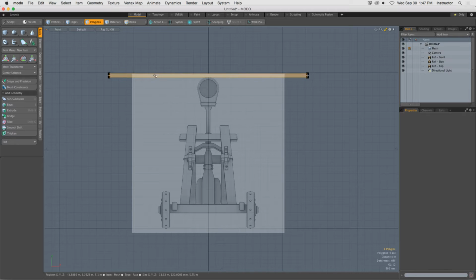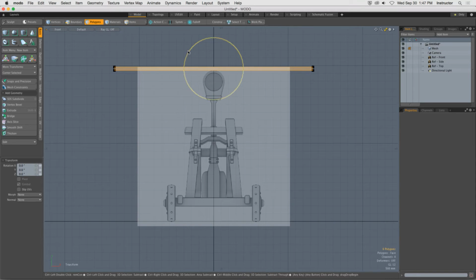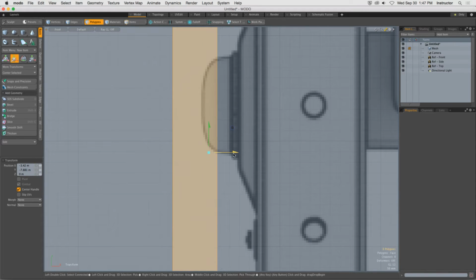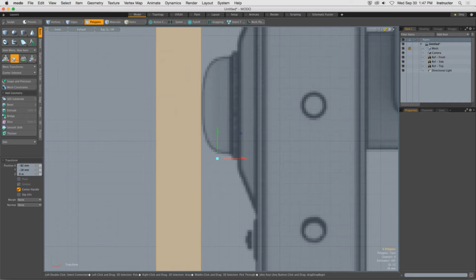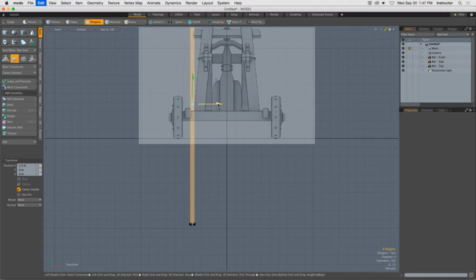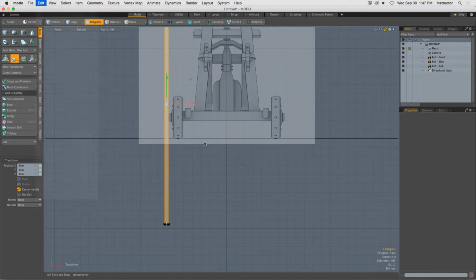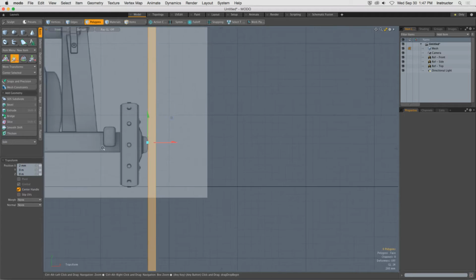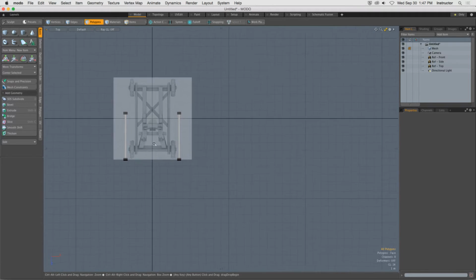I'm going to recycle this reference plane, rotate it 90 degrees, yoink, there we go, and then just place it at the alignment area that I'm after, maybe right around and there. Wonderful, okay, great. Now I'll simply copy it, paste, move the duplicate copy, there we go, to the other side and define its placement in reference to the image, right around and there. Wonderful. Okay, let's look at our image from the top.